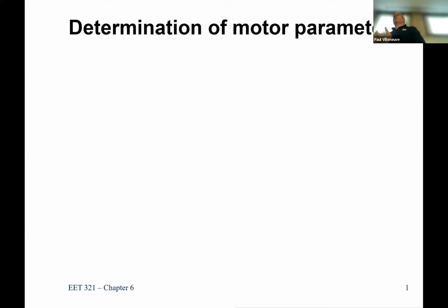We did the equivalent circuit for the transformer, right? We did some no load and load loss tests. We did some tests for the synchronous machine where we did open circuit and short circuit characteristics to get those. So similarly, we have to do the same thing with our induction machines, and we're kind of limited as to what we can do. We can do a couple of tests from a perspective of applying a voltage and looking at speed, but that may not necessarily be all that useful for us.